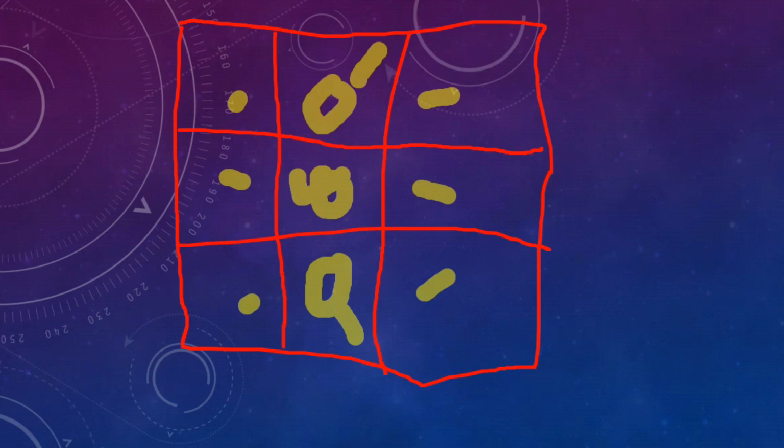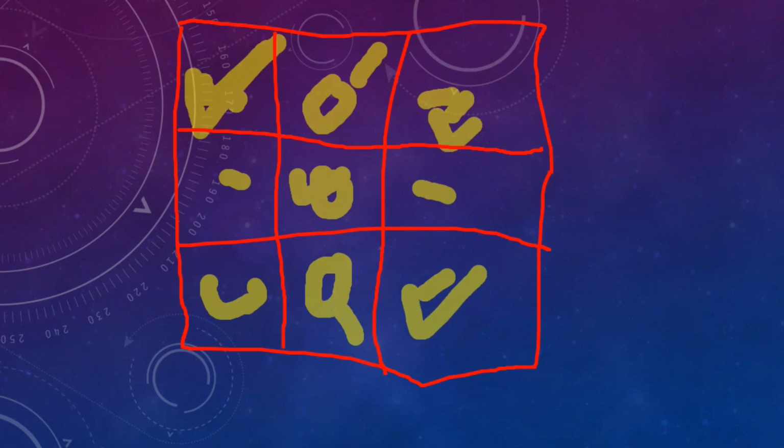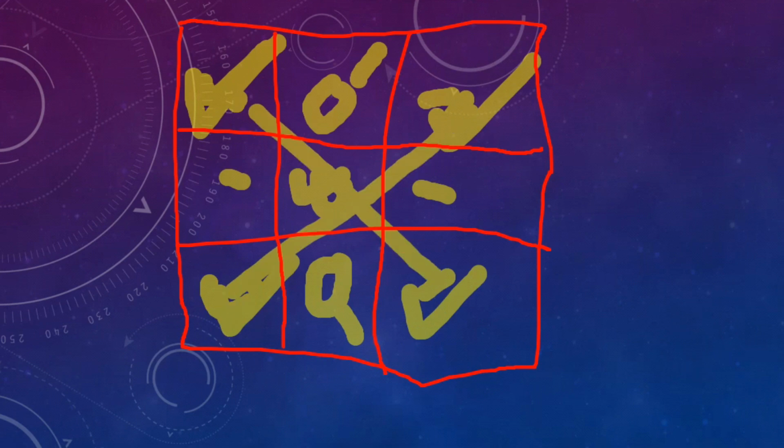If I install 2 supply diffusers at this point and this point, there will not be a proper balancing of airflow. So you have only one option: install the supply diffuser here, and go with the return diffusers here and here. So it is adjustable based on the site. There is no fixed rule for the minimum distance between square diffusers. But practically, if possible, you can go with a minimum of 1.5 meter difference between two diffusers to avoid short circuiting.